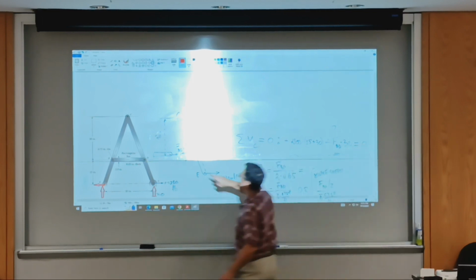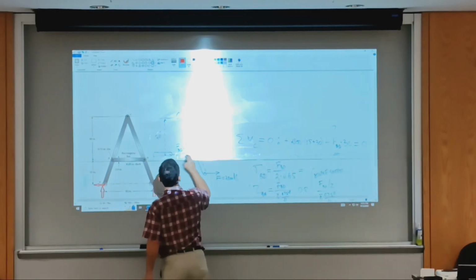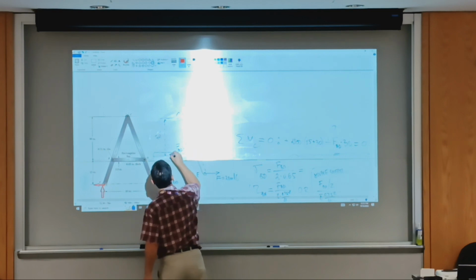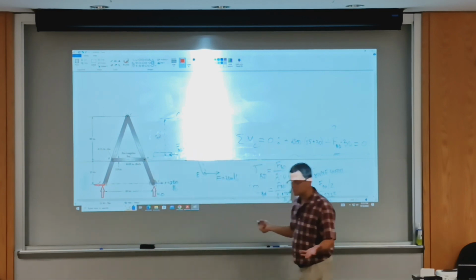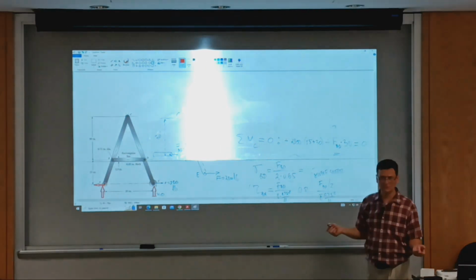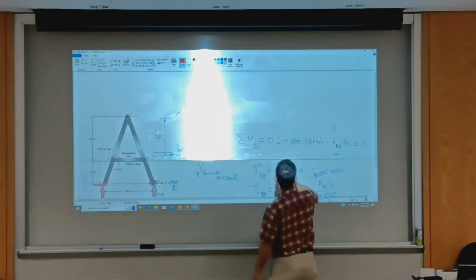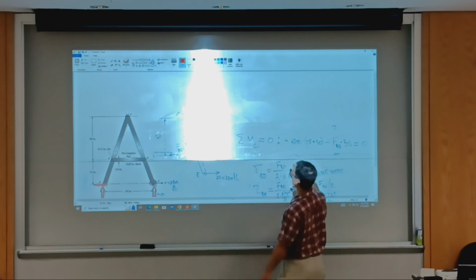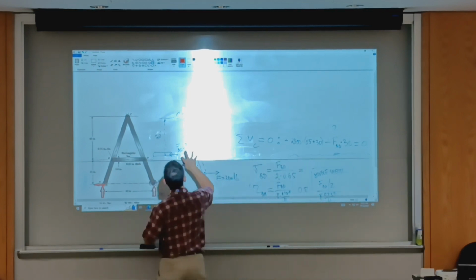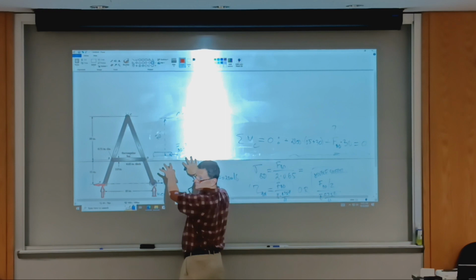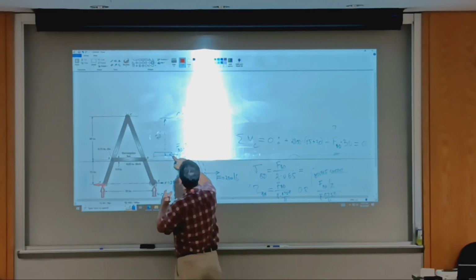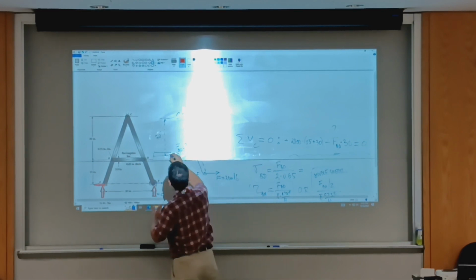Yes, okay. So you assume, I understand your question. So you're just assuming this and this, but not knowing. Yeah, it's human. You don't have an intuition, it goes all the way to the end. So that will change this into a positive. You get a force that is negative. It means that you have to go to the free body diagram and you need to flip it. You understand what I'm saying?